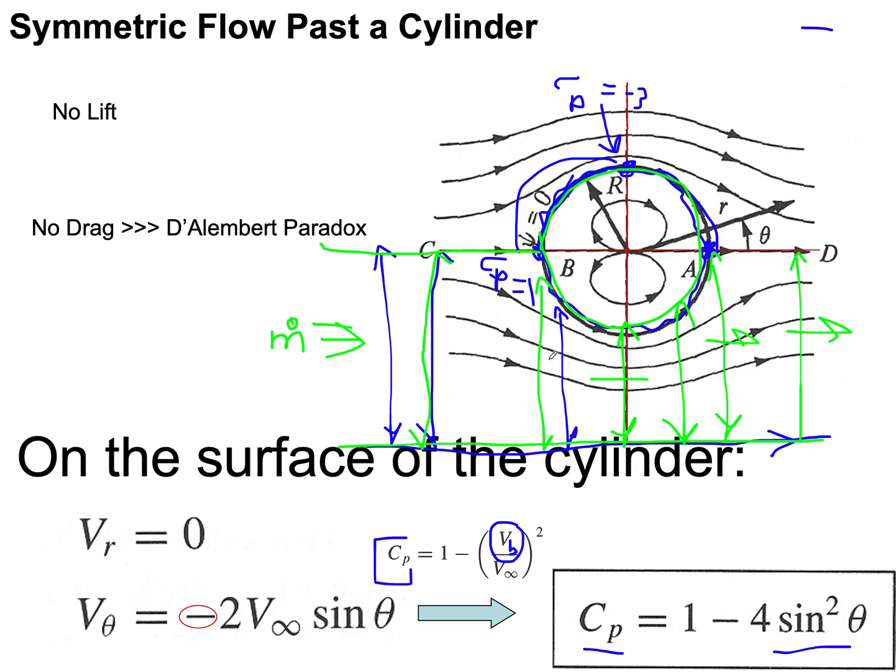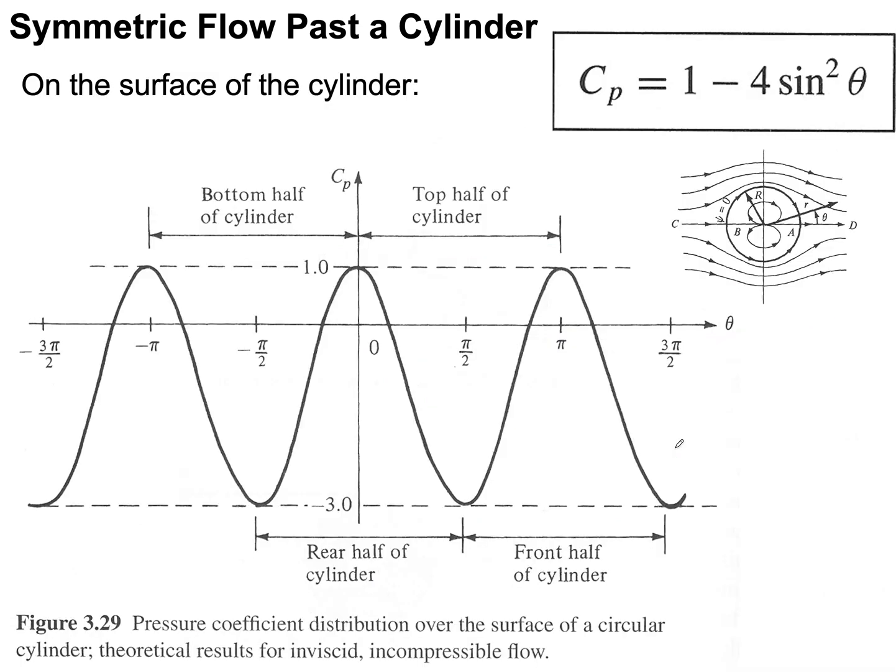So you'll see I get a region of a favorable pressure gradient. The pressure gradient is trying to push the flow to help me because the pressure is high here, it's low, so it's helping out, while the pressure is low here and pressure is high here, so it's actually trying to retard the flow. Remember this favorable and adverse pressure gradients. We're not talking about pressure, but pressure gradients, difference in pressure with distance, because it's going to come handy when we discuss the actual flow around a cylinder.